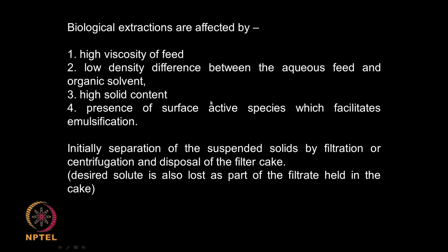So, because of all these reasons you may have problem in extraction, but then extraction is one of the best methods in biological systems. Like I said, your proteins, carbohydrates or even enzymes may be very thermally labile, and you might not be able to use techniques like distillation or any other high temperature operations, whereas liquid extraction you can work with room temperature and even with buffers actually.